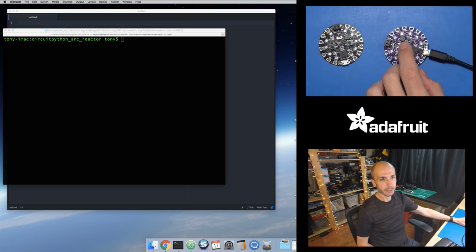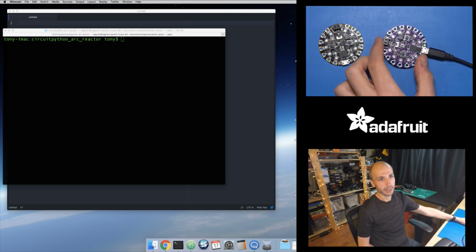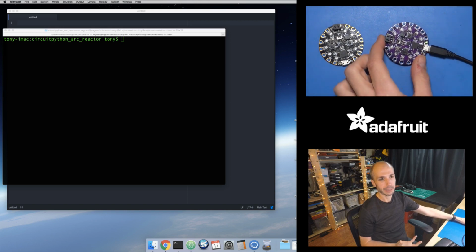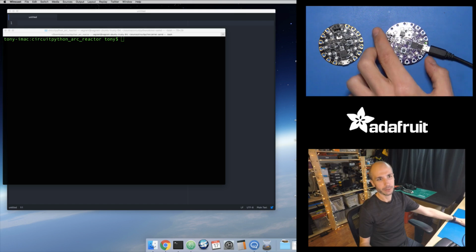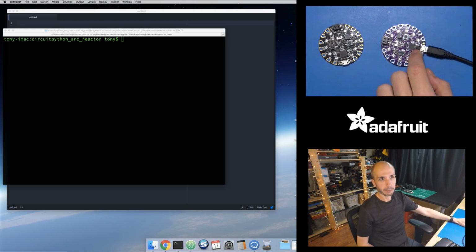And it also has a little serial SPI flash ROM on it, or EEPROM, which basically you can program the memory of that flash chip. And with CircuitPython and MicroPython, when you have a bit of flash memory like that, you can make it look like a file system where you load your Python code. So I believe this board has a 2 megabit flash, but who knows, the final board will probably be a little bit different.